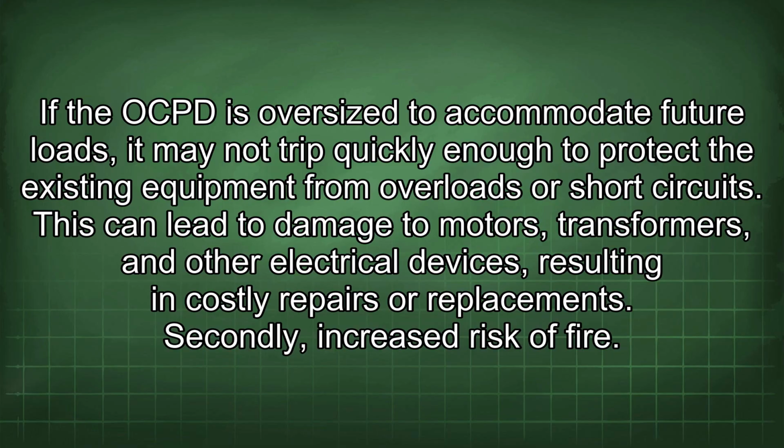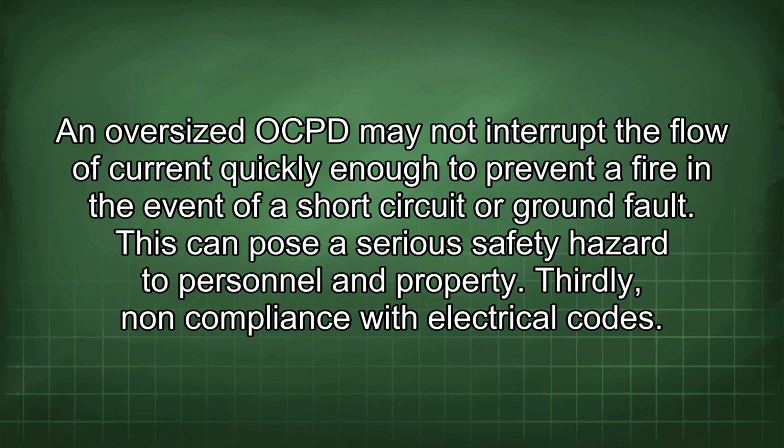Secondly, increased risk of fire. An oversized OCP may not interrupt the flow of current quickly enough to prevent a fire in the event of a short circuit or ground fault. This can pose a serious safety hazard to personnel and property.